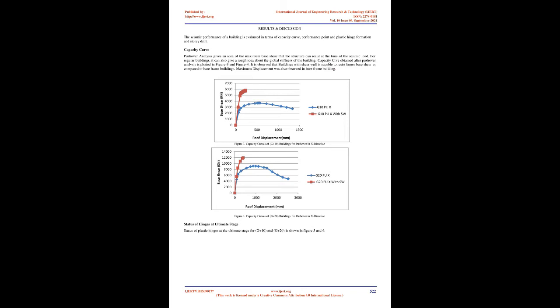Two pushover loads, push X and push Y, were defined as displacement controlled. The maximum target displacement of the structure was kept at 4% of the height of the building. Both pushover loads were run from final conditions of dead load.